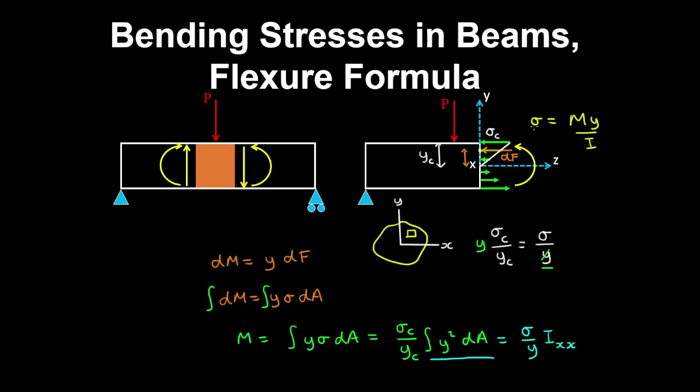And because we want tensile bending stresses to be positive, at a negative y value along that section, and where the sagging moment is positive, then positive by negative will give a negative stress. So to make the tensile stress positive, we'll put a negative over here. So where y is positive, we have the sagging moment causing compression, and because M and y will be positive in this case, we have the compressive stress being negative.